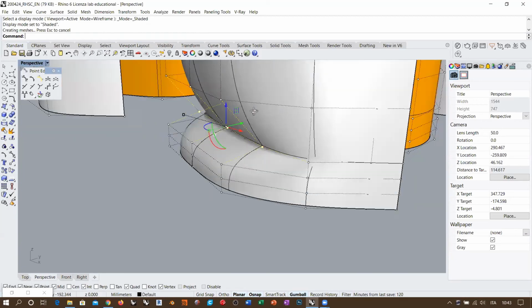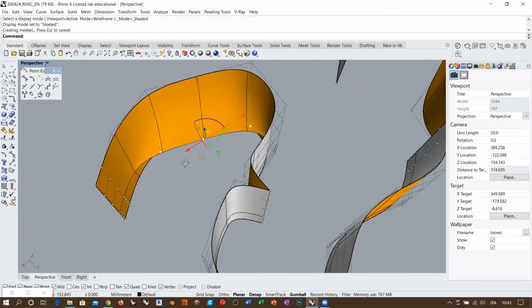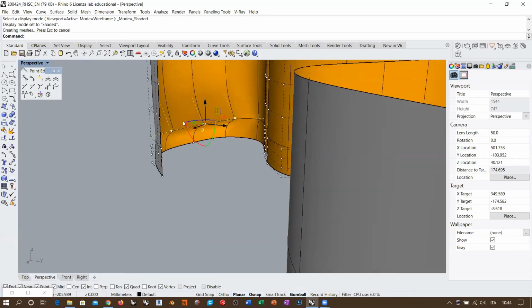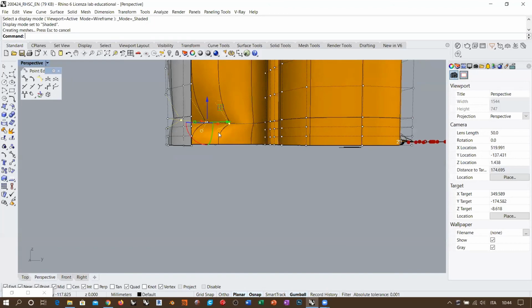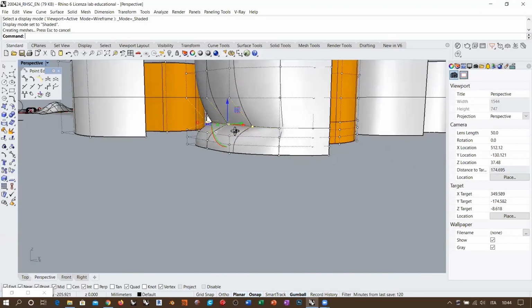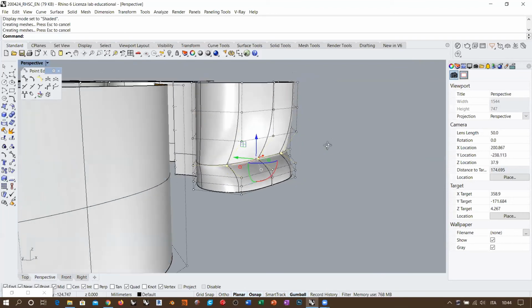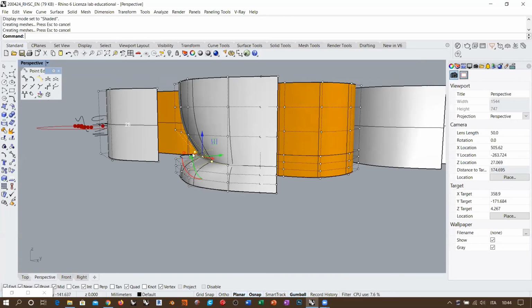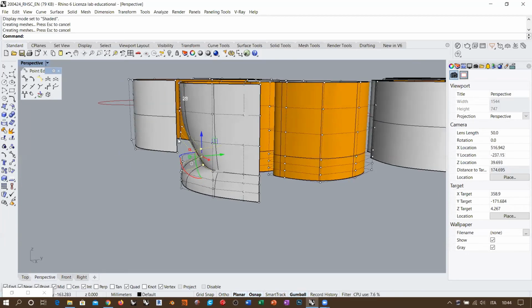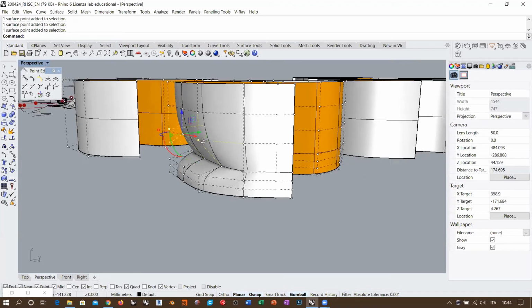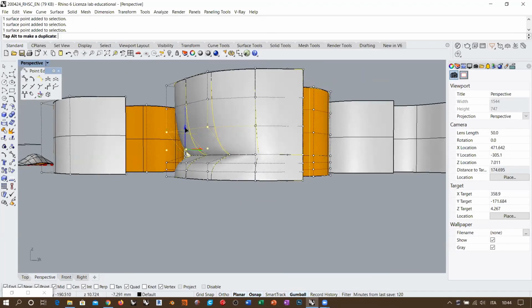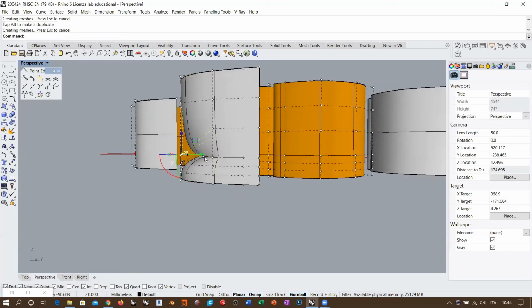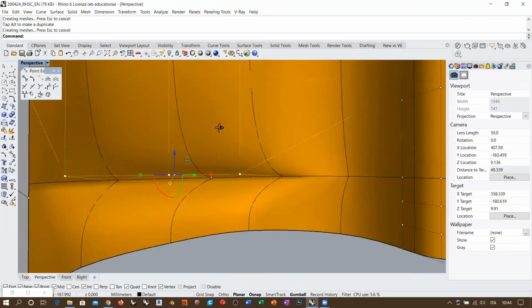The kink becomes visible only where you displace the control points. And so if I want to concentrate this kink in order to make it look like a seat, I don't care about the lower part, but I need this part to be more flat and horizontal, right? So what I can do, I can take these control points in this area, which determines the tangency starting from the kink up. So I can take these 3 control points, 1, 2, and 3, and bring them down like this to the horizontal, more or less. So I'm setting this tangent like horizontal. You see that the surface is already reacting to this.